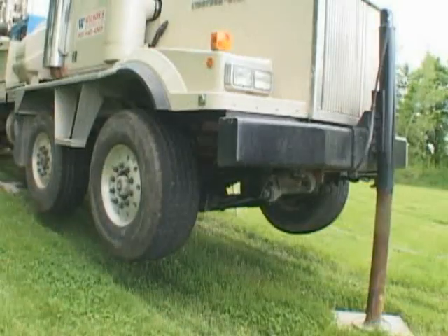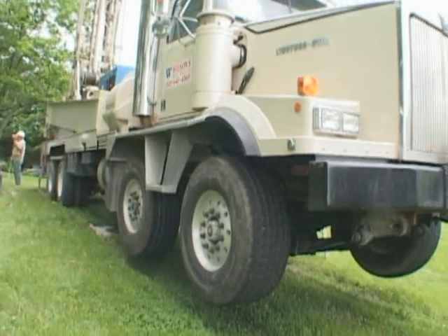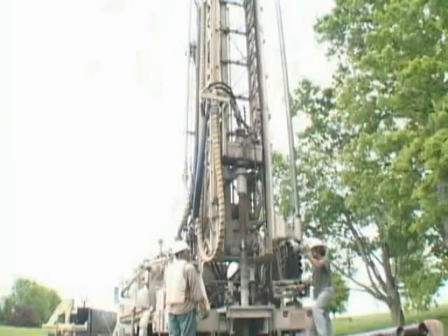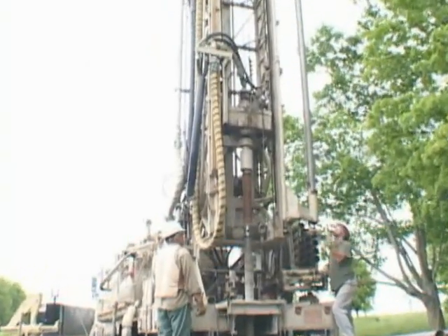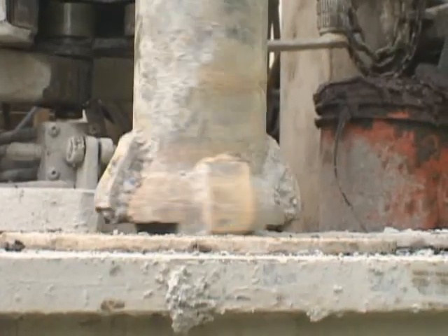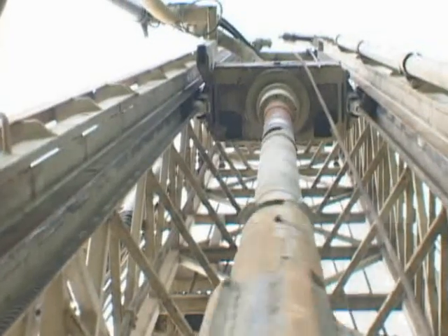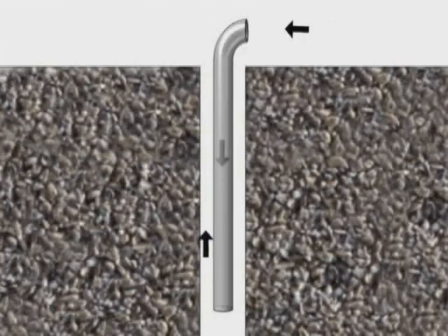The rig is powered by the truck engine itself and requires significant horsepower and resulting fuel supply to perform the drilling operation. However, the conventional rotary drilling system offers excellent penetration rates, quick setups, and either rotary cut or rotary crush cutting actions. The rotary crush cutting action is being performed. The rotary drill uses the conventional or direct circulation path for the flushing media.